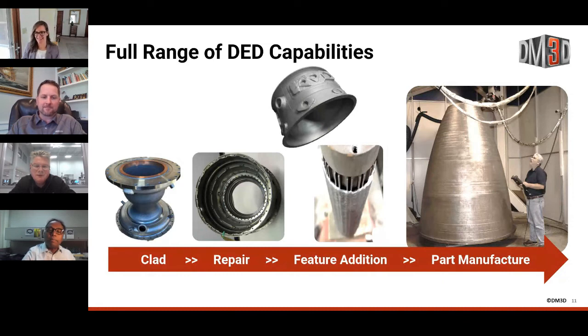So, Bhaskar, could you, for example, make a part out of stainless steel and then put, say, stellite bearing surfaces on it? Yeah, absolutely. So you make the bearing along with the part. Correct. And we have, Giles, not so much for parts, but we have done a lot of multi-material tooling applications for die casting tools, as well as some injection molding tools, typically copper steel combinations.